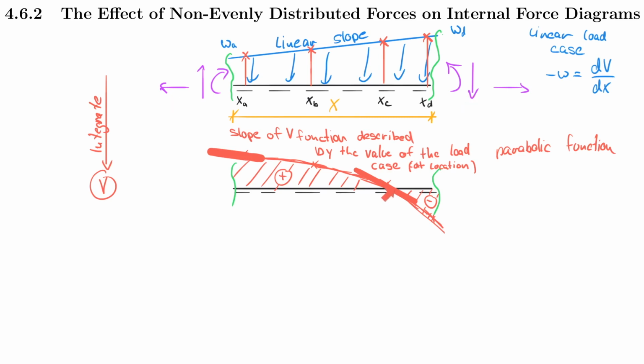And so you hopefully understand that this entire shape could move all the way down, so that everything is a negative shear force. It could be completely up, so that everything is in positive shear force, or we can move this anywhere along this line, depending again on what happens here and here. However, when we move on to the moment now, this of course has a very important impact on the moment diagram, because you know that your moment is really the integration of the shear force.